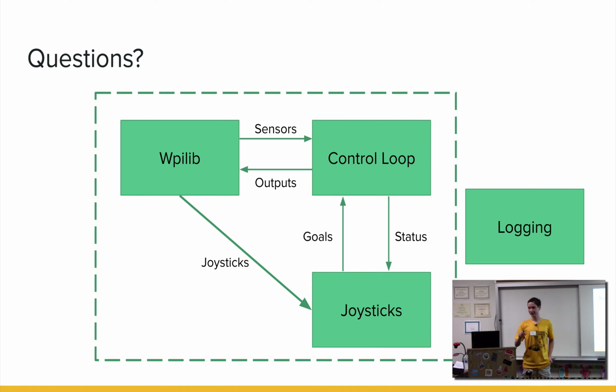Anyone? Yeah? Can you explain how you implement the process separation on the RoboRio? Yeah. So basically each of our systems, for example, the control loop or the superstructure, the joystick reader, those are actually separate C++ executables, and so those each have their own main method. The way that works is we write a superstructure main program, and then what that does is it instantiates AOS, which gets it set up to plug into that message system, and then it starts running the control loop, and then when something tells it to stop, then it stops and closes out.